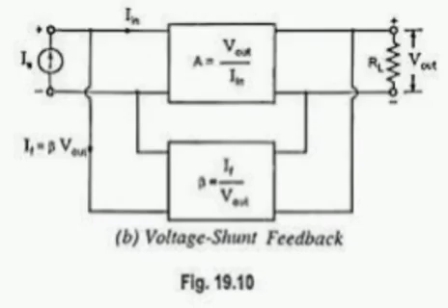Amplifier circuit using FET and MOSFET. All the formulas are the same whether it is designed using FET or MOSFET. Common source configuration: voltage gain AV equals V0 by Vi, which equals numerator minus mu RD, denominator small rd plus capital RD plus (1 plus mu) into RS. So the whole equation is minus mu RD by (rd plus RD plus (1 plus mu) RS).